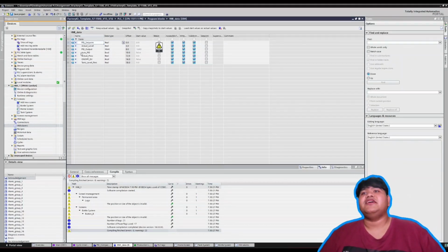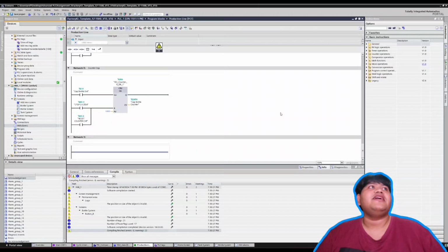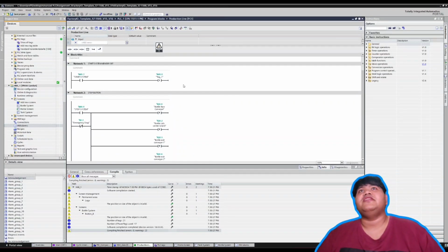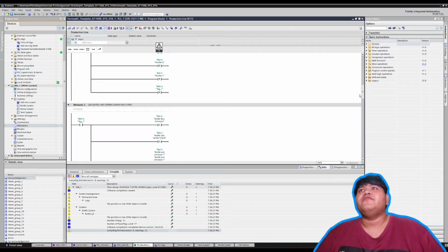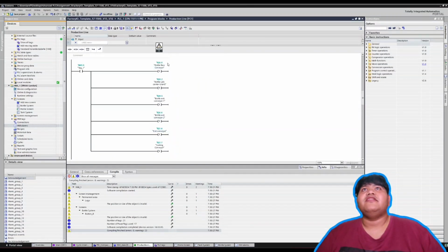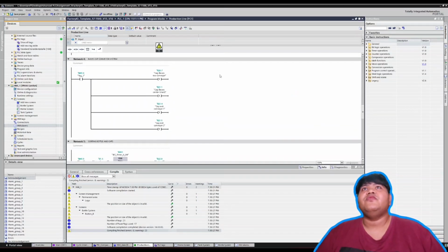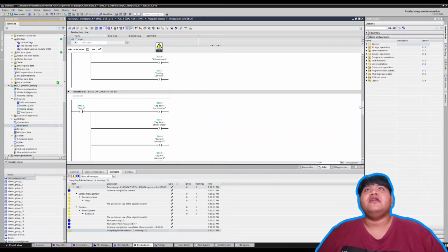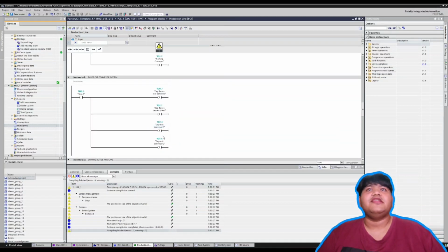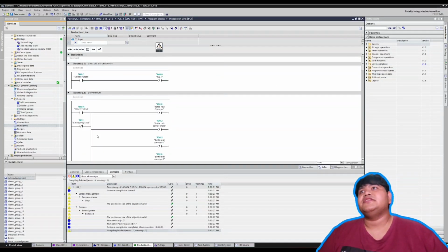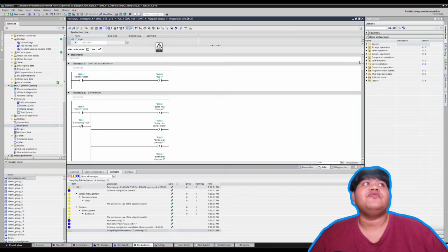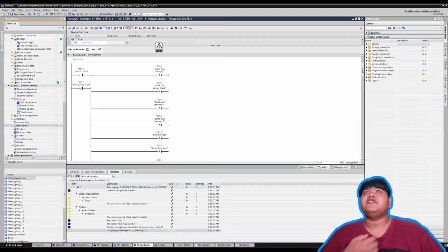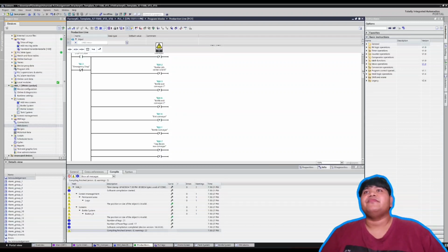This is the HMI data. For the production line, when I press the start button, the memory will set all the conveyors, the bottle lid center start, and also the cap base center start and the conveyor in the cap base. When I press the stop button, which is the physical emergency button, it will reset all these components.